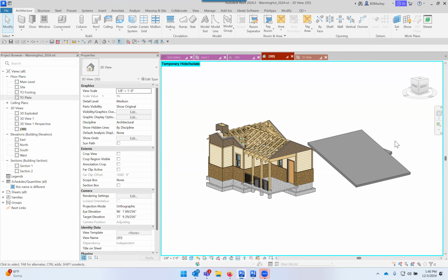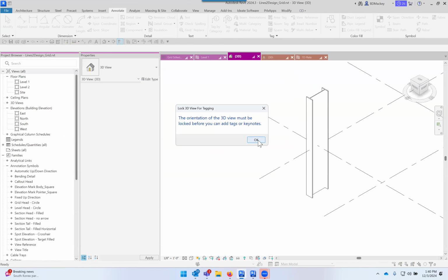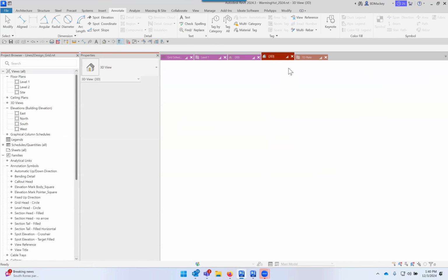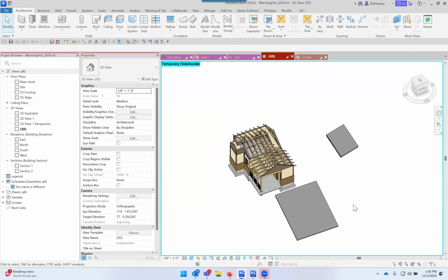The one thing I have found to do, Brian, and you can try this, is have a reference plane or something set up. So sure, I guess I can do it in here right now. This has nothing loaded into it. I'm going to do it in here. So if I were to do some sort of dome or mass or something like that, what I'll do is I'll create a reference plane where I want that to be. And then oftentimes you can place that object nearest to it. And then you can use your align commands to align it either in plan, but more than likely you're going to have to do it in section because you've got to rotate it around.